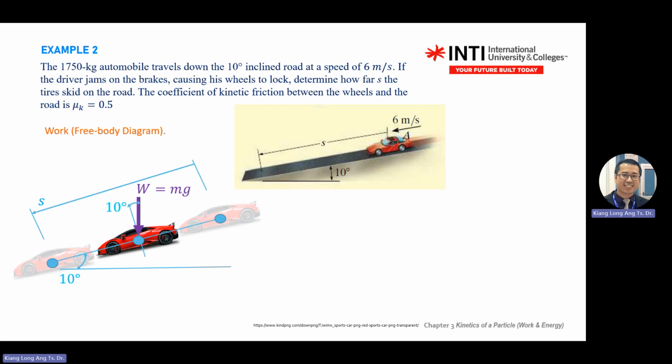So here you need to consider the normal force already, because it gives you the friction force, with the friction coefficient. You need to find the normal force and friction force. In this one, you sum up all the normal force in one location, in one diagram. Although you have a front wheel and back wheel, normally for particles we only look at one point. We combine N1 and N2 to become one N. Okay.